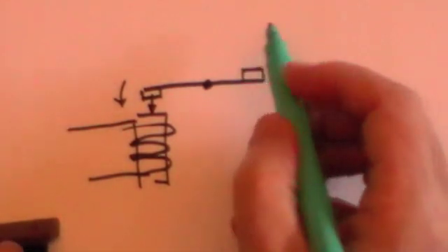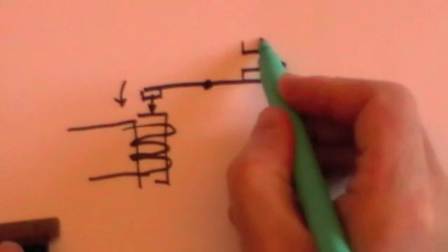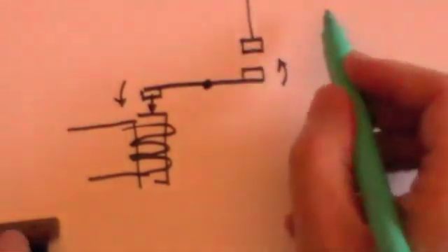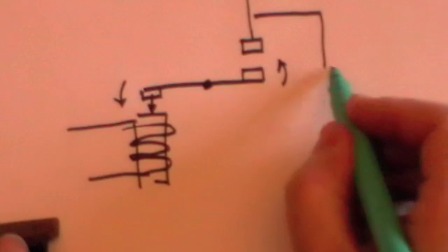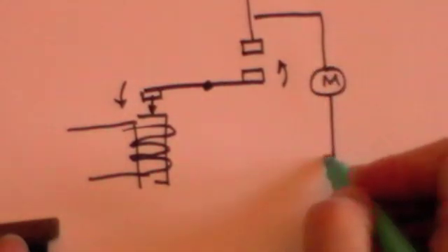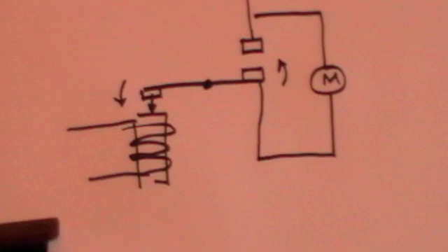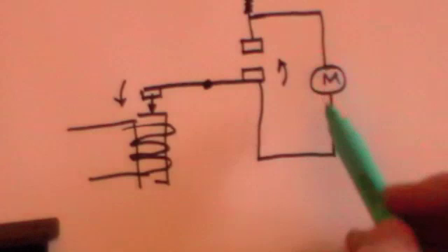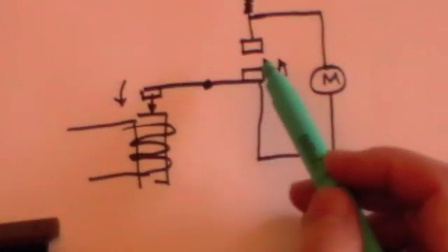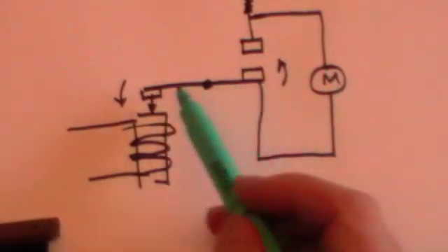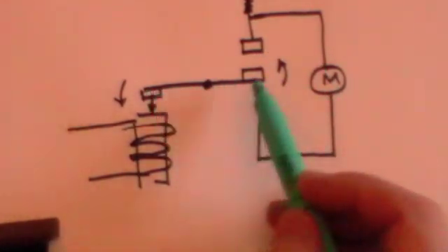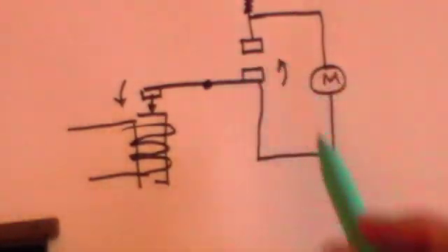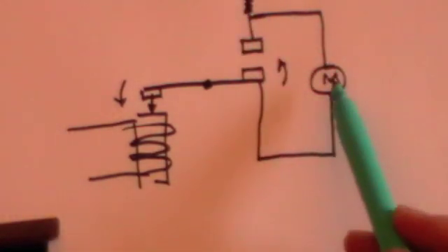Now suppose I've got a piece of metal here linked to the circuit in which the motor is, like that. What will happen is the motor will only come on when those two join. In other words, when there is a complete contact between the two. So ordinarily, there'll probably be a spring on this to make it sit nicely like this. So ordinarily the contact is open, consequently no current flows, consequently the motor doesn't come on.